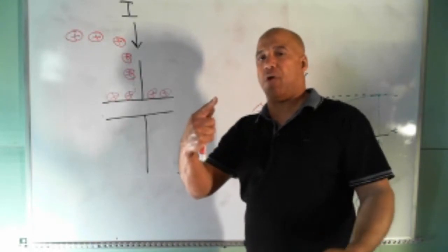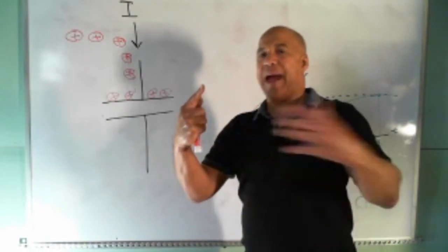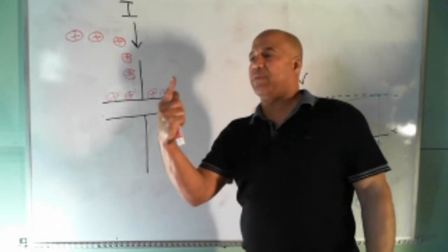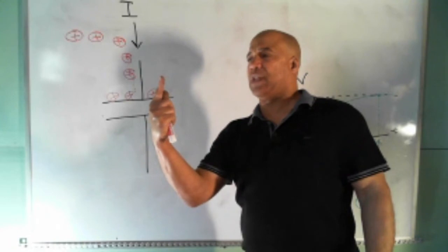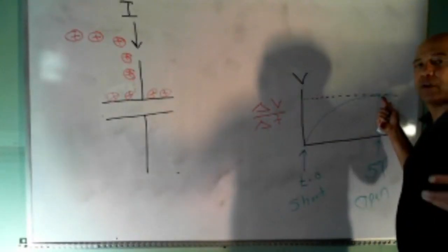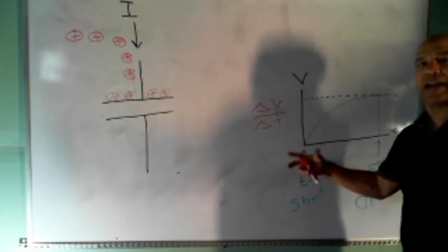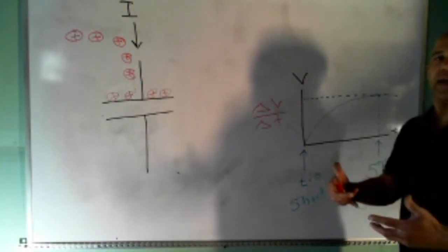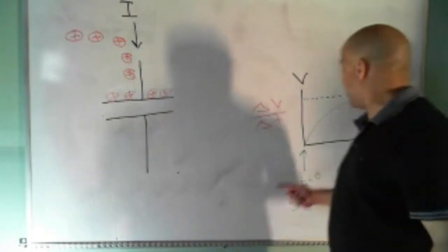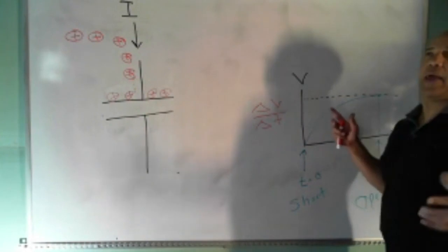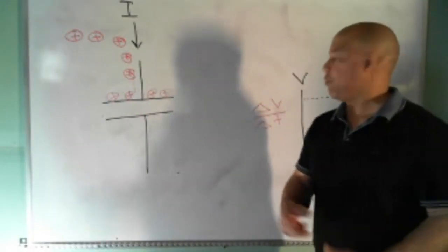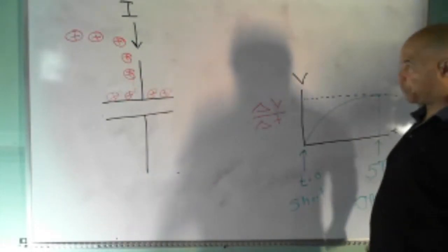But the more air I put in it, the more back pressure I get. The needle's going to slow down to the point to where it's going to start to just really, really slow down. So I'm getting up this curve right here to the point to where the pressure from the compressor and the back pressure from the air tank equal each other. No more air can flow into the tank. If you never worked with an air tank before, you don't know what I'm talking about. But if you have, that's exactly what's going on here. A capacitor acts just like an air tank. You're trying to put air in it. It works the same way, same exact way.